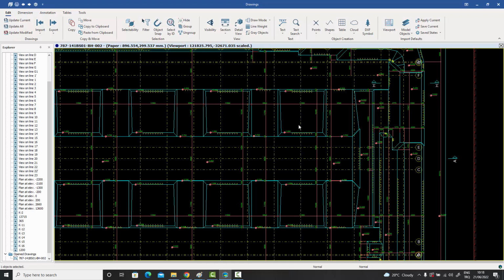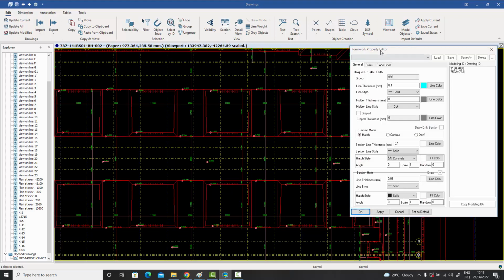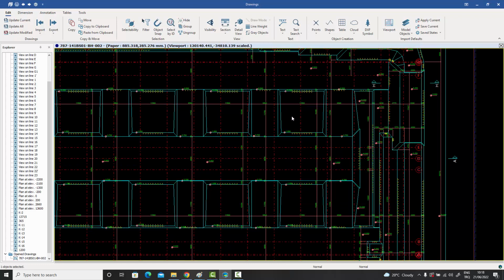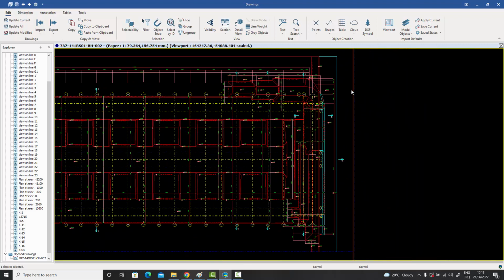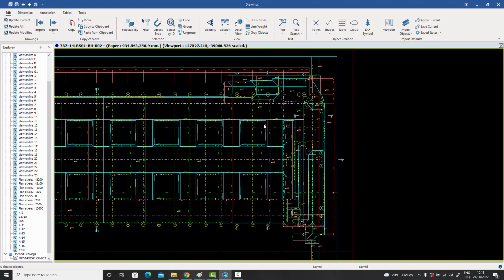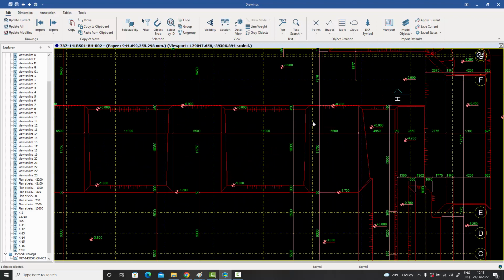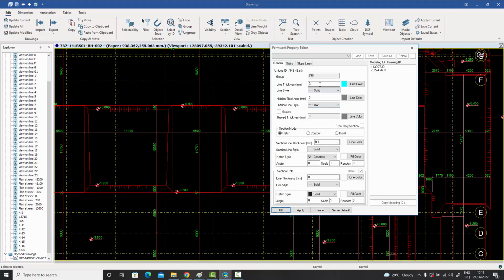So this option is very useful because it allows you to create excavation drawings, if you will, using the same formwork object. And the formwork object, let's go back into the dialog box. Let's go quickly over it once again. On the right hand side, you will see the objects which have been merged from the model side. If you want to select any particular one of them, all you need to do is press the Alt key and select it, and that particular one will be selected. So right now you can see that this one has not been selected. Similarly, if I were to not press the Alt key and select the object, then the entire thing would be selected.